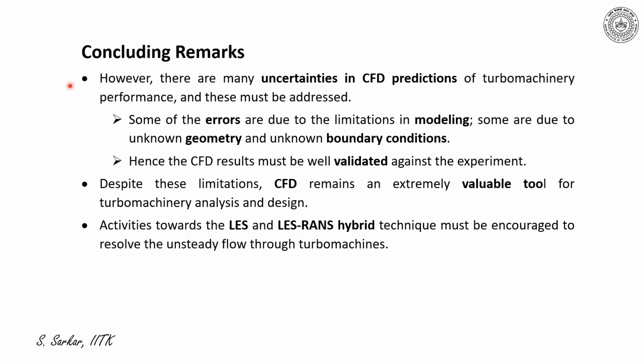However, there are many uncertainties in CFD predictions of turbomachinery performance, and this must be addressed. Some of the errors are due to the limitation in modeling, some are due to unknown geometry and unknown boundary conditions. Hence, the CFD result must be well validated against experiment. Despite these limitations, CFD remains an extremely valuable tool for turbomachinery analysis and design activities. The LES and LES-RANS hybrid technique must be encouraged to resolve the unsteady flow through turbomachines.